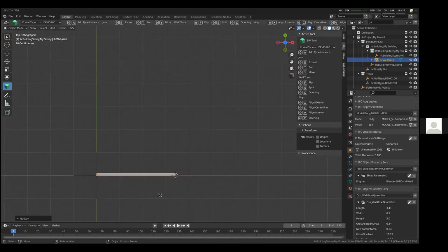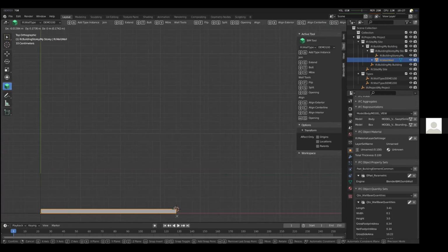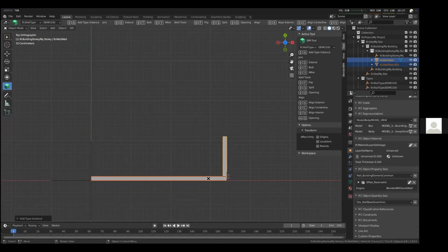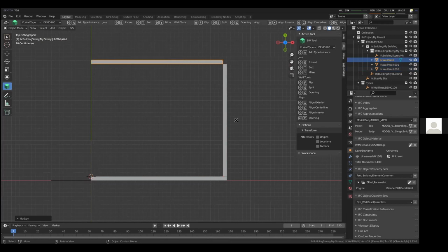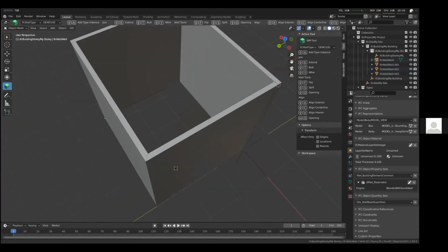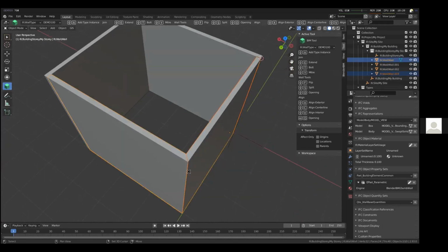So now, for example, if I go and create another wall, you can see it automatically worked out that it's a 90-degree attachment to that wall. So I can go take that wall, extend them out here, go add another wall. And let's say I want to extend we'll take this wall, extend them out here, and I'll just duplicate that wall here. And let's say we want to change that to a miter joint here. Great, now we have a miter joint. And you can see how simple and...